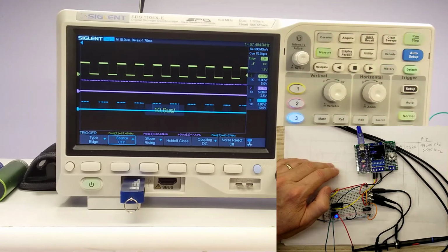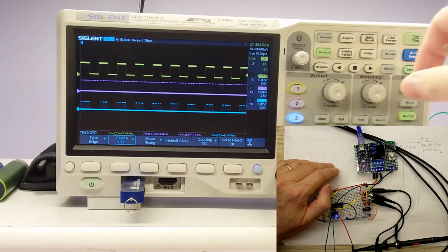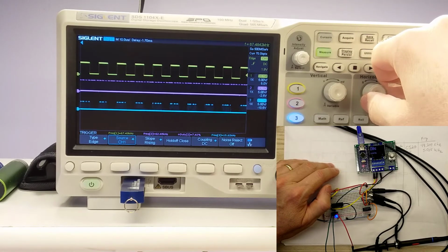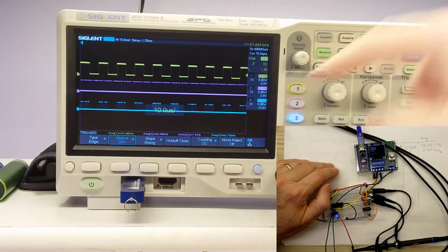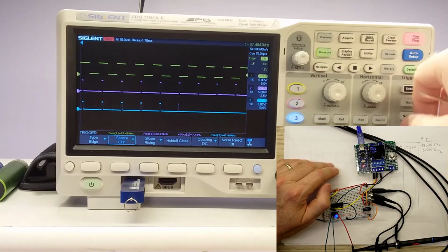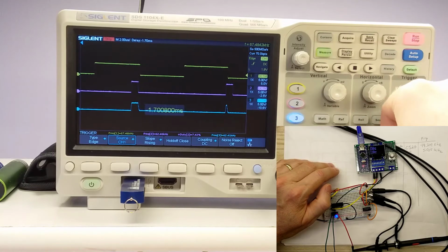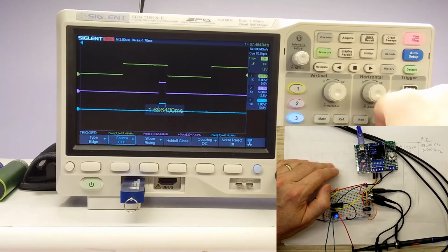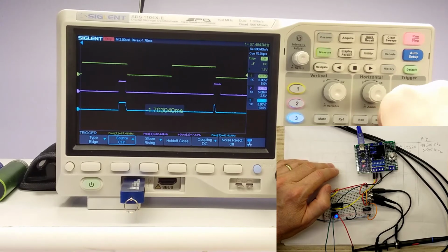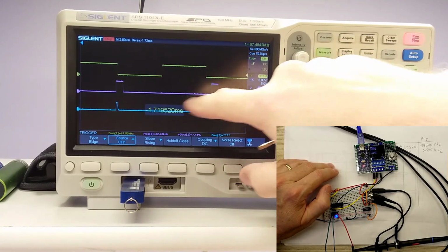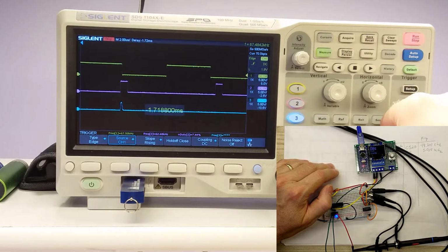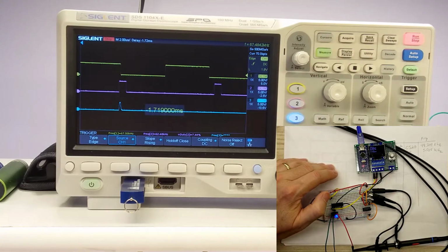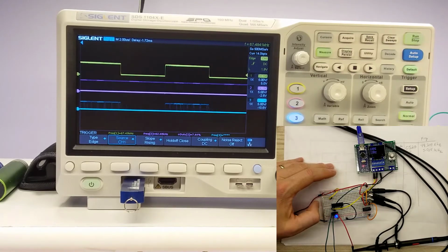So now I've got channel 1 coming in at about 67 kilohertz and channel 2 at around 62 and a half kilohertz. And as you can see, there's a lot of kind of movement on the scope. We'll just go ahead and pause that so we can zoom in real quick. And now you can see here, much faster, you can see where we get some little indications where both lines go high briefly and then drop again. And you can see right here is where they're no longer coinciding on the two outputs, but you can see there's just a really light little bump right there on that one. So at 67 kilohertz, it appears to be running fine. Let's crank it up a little higher.